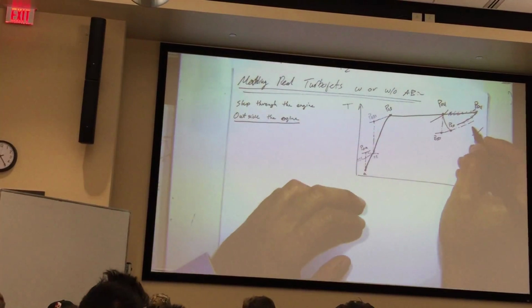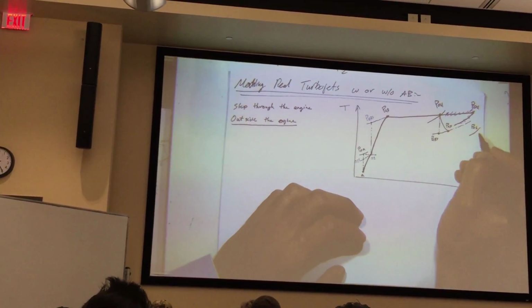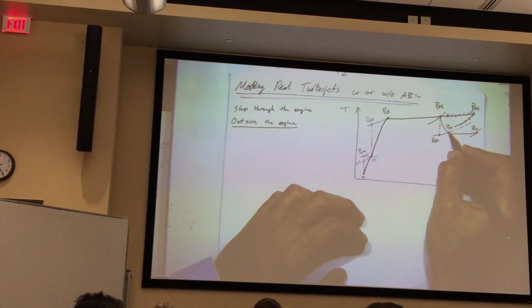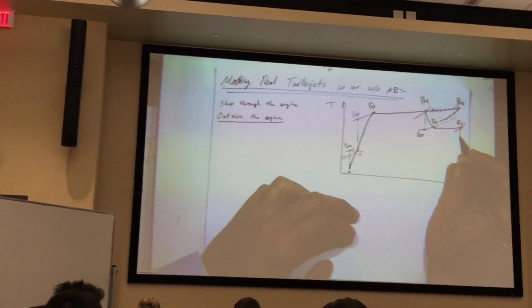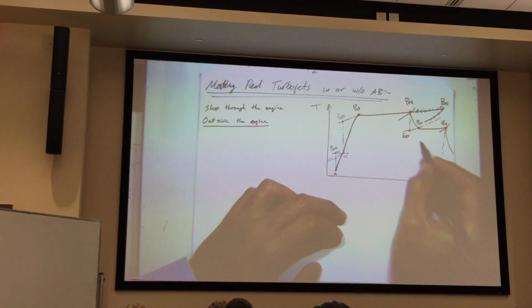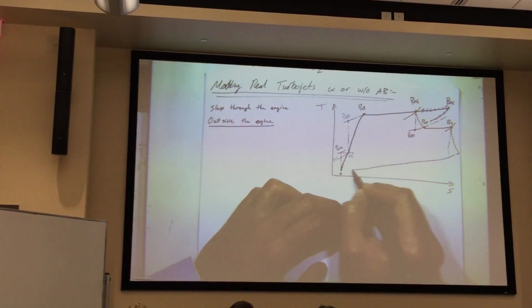So I'm going to name this PO6, which is a pressure loss, and this is what I'm going to be adding as heat through my afterburner. And then I come to isentropic expansion versus real expansion, same exact principle, through my CD nozzle, and then I'm back into this curve right here.